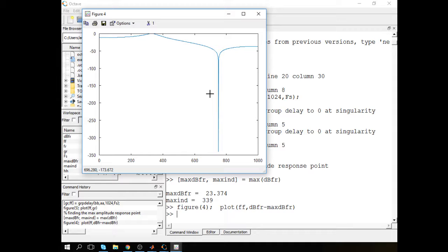Okay, how to scale the system? This is just the plot. You actually divide the numerator part. So basically, you will be affecting this value here. You rescale this value, meaning that a0 must be 1. So it means that you can scale only the numerator values, so the feed forward values, the Bs.